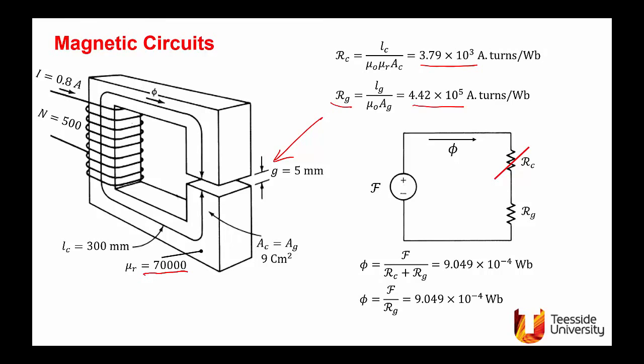This is a similar situation we have. We use the iron core here to carry the flux, but this flux is supplied to the air gap, which is the highest reluctance by far in the circuit. In other words, we can assume that the magnetomotive force Ni is acting on the air gap approximately. In this case, the integration of H dot dl will be H multiplied by G. This part here is the integration of H dot dl. Approximately it will equal H multiplied by G. Ignore the rest of the part of the integration.